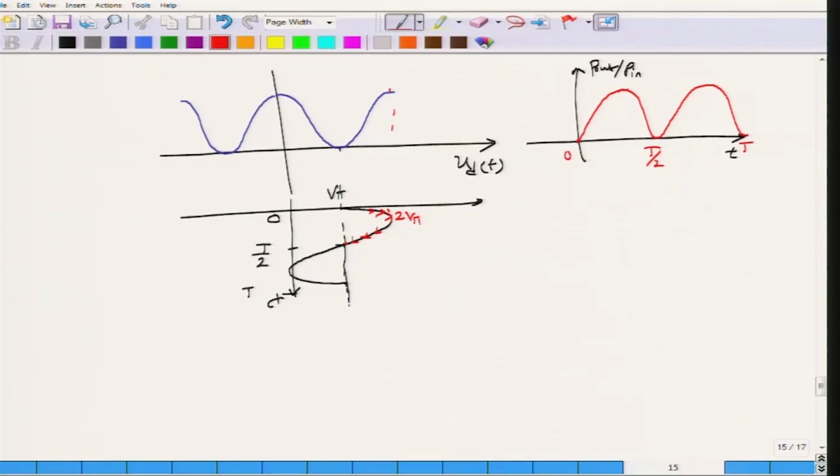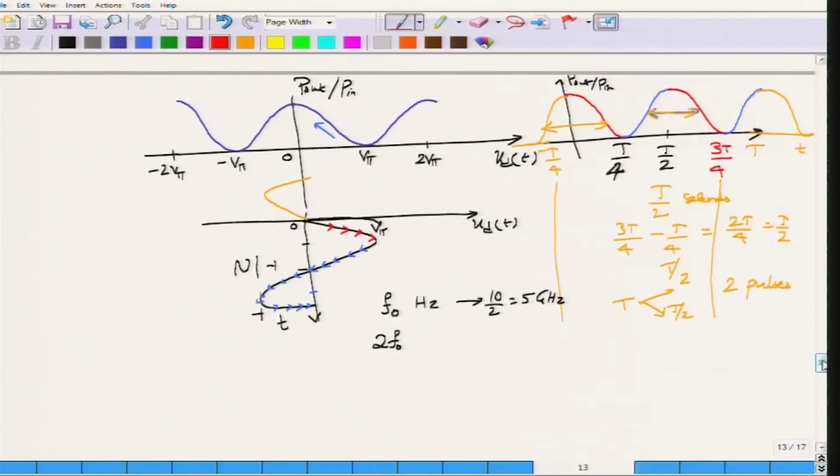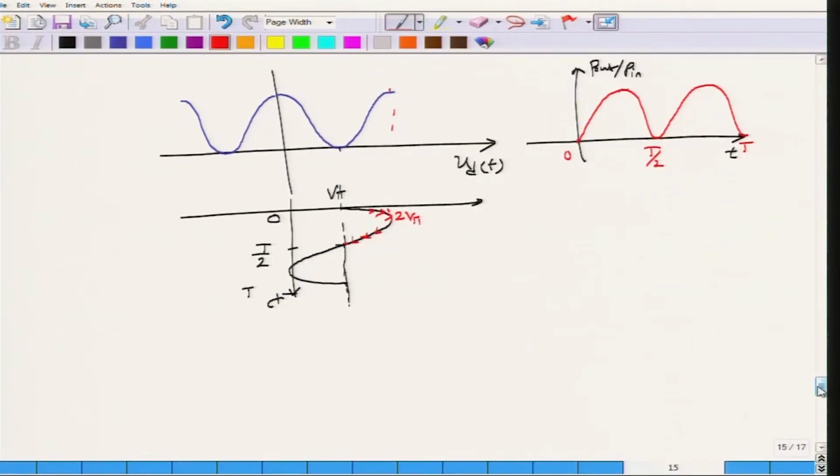Okay, so if you compare these two waveforms, you will see that the areas occupied by them are slightly different, although I have not shown it very nicely. These two are therefore called 33% and 67% waveforms, which simply indicates the percentage area that these pulses carry compared to one period. Okay, so we will not go further beyond this pulse shaping. We will talk about pulse shaping in the electrical context later on, but for the optical pulse shaping we will stop with these two pulse shapes, because these are easy to generate and therefore widely used.